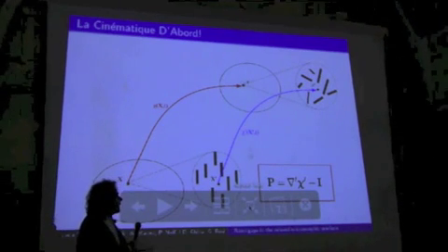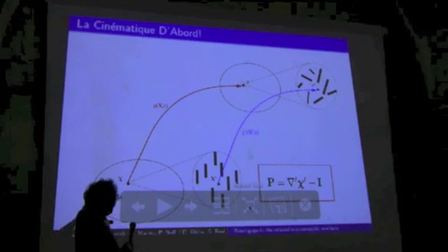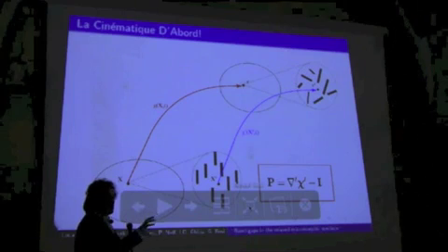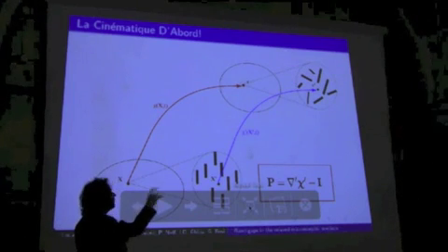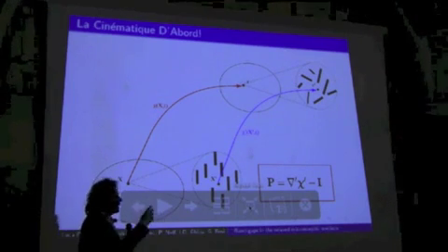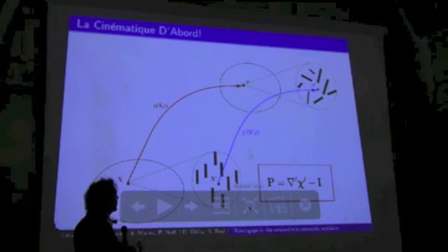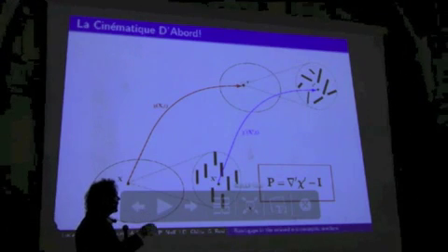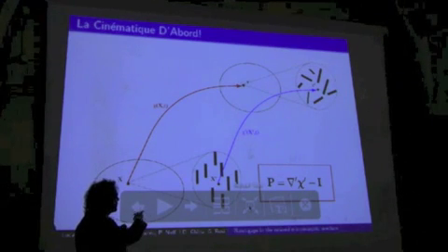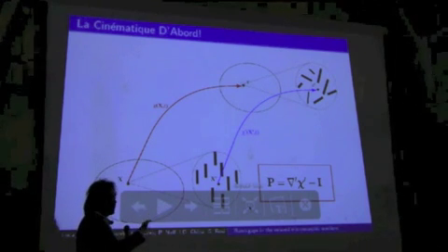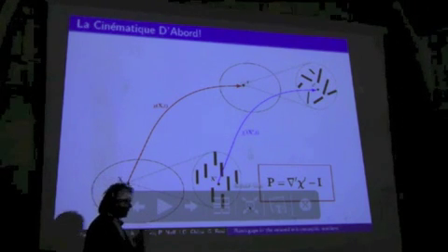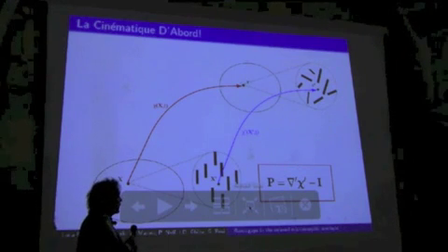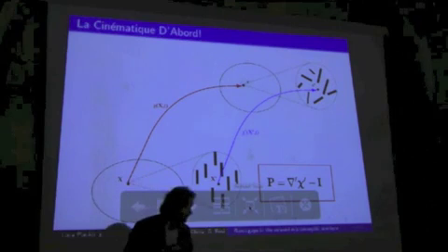But in a micromorphic model, every point in the reference configuration corresponds to a certain representative volume element that can be displaced somehow, and in a general micromorphic model, this displacement can be not only rigid, but can include some deformation evaluated by this tensor P.